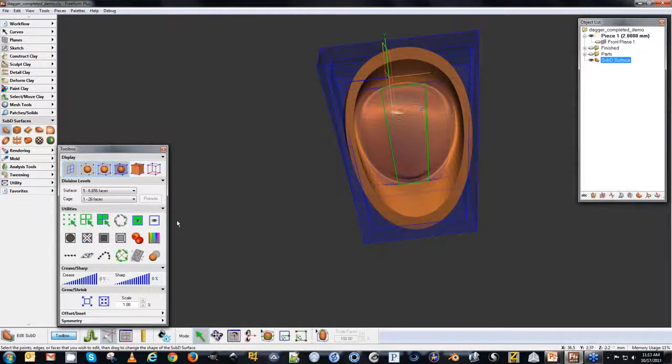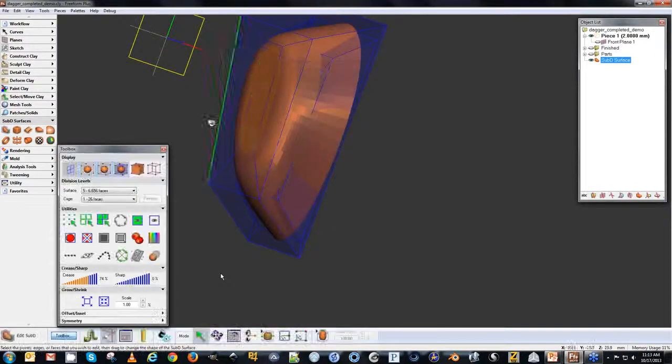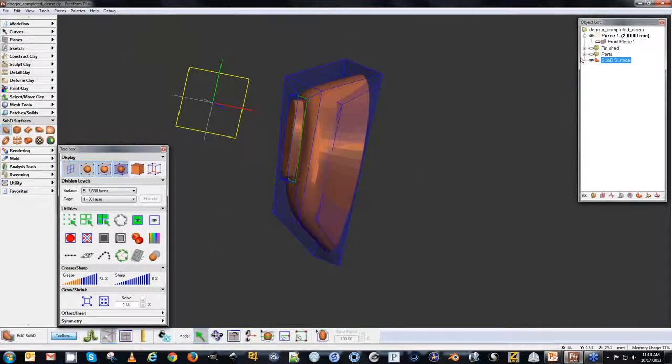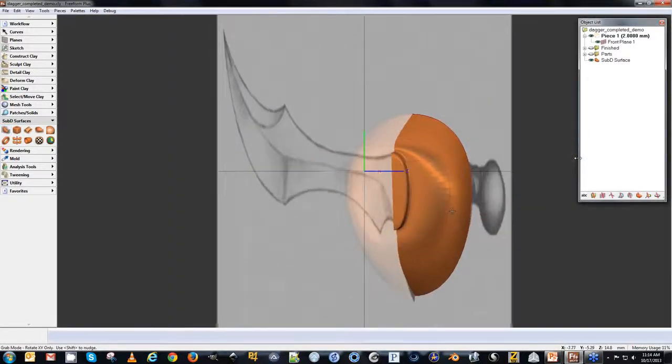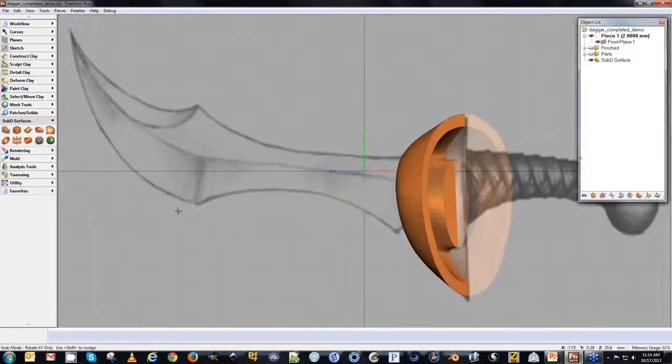And then if I do a selection, crease this up, do the same on the outside, I will select this, make an extrusion, select the edges I want to crease. And right there, let me click off of this and turn back on my background plane. We have a really good representation of the sword cross handle that we want to make.